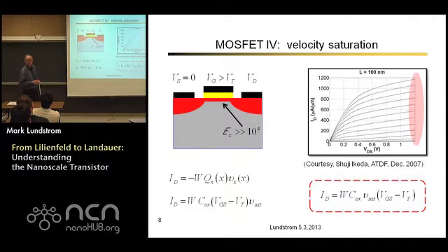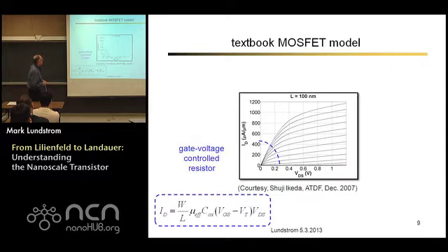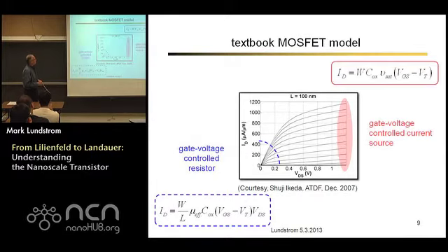And if you see a transistor like this, and if you see the current increasing as Vg minus Vt to the first power, just linearly with the gate overdrive, the amount of voltage above the threshold, you say, aha, this is a velocity saturated MOSFET, right? So I know what I'm dealing with. Okay, all right, so these are the textbook expressions, all right? Everything is nice.